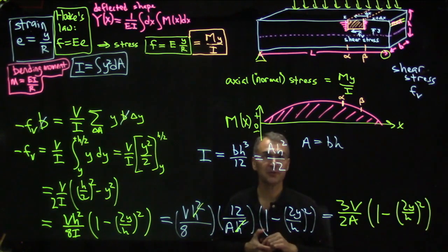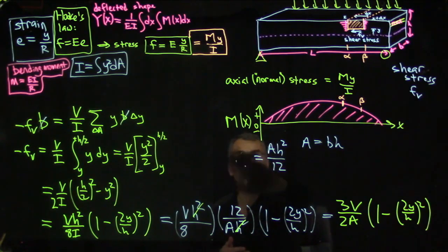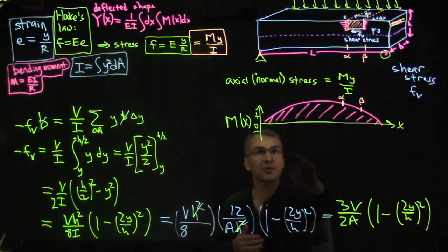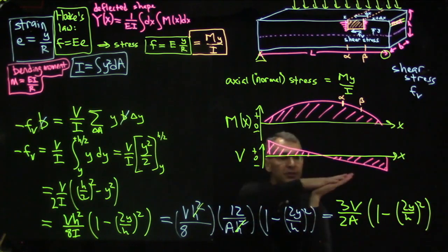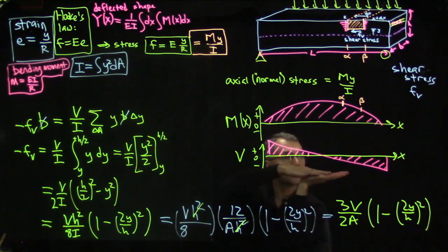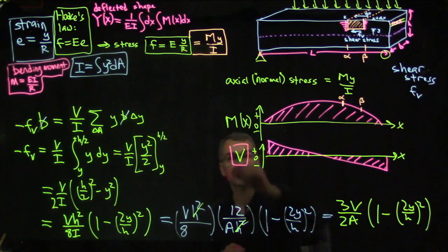That was a pretty confusing mess of math, but what is this actually telling you? It's telling you that if you have a rectangular beam cross section, and a simply supported beam with uniform load, which is a nice, somewhat typical case, then the shear stress, the stresses trying to pull those parallel playing cards past one another, the forces internally trying to slide those internal playing cards in the deck of cards parallel to one another, are largest where this shear function V is largest.